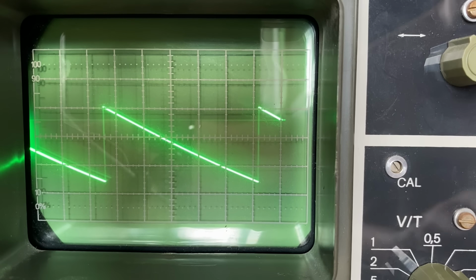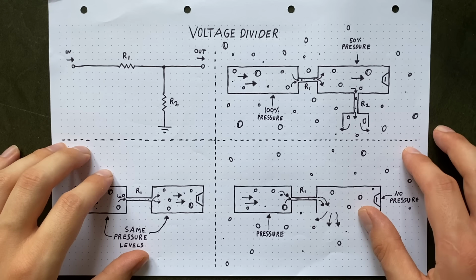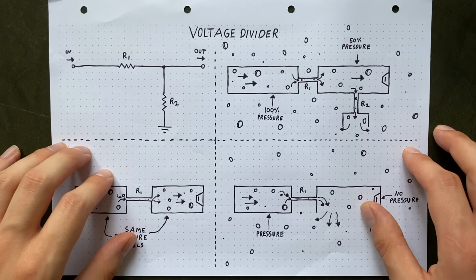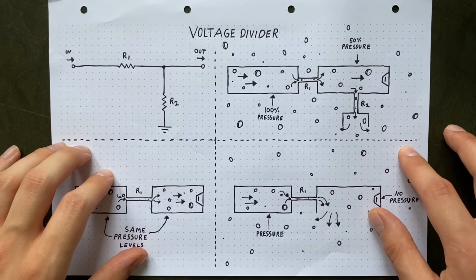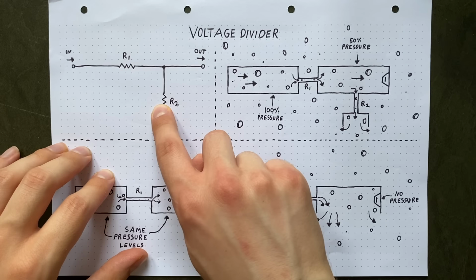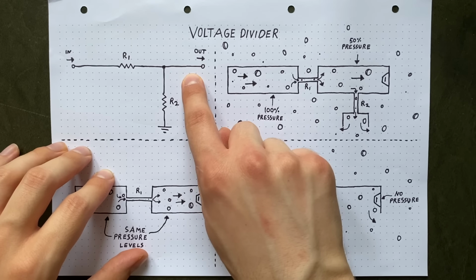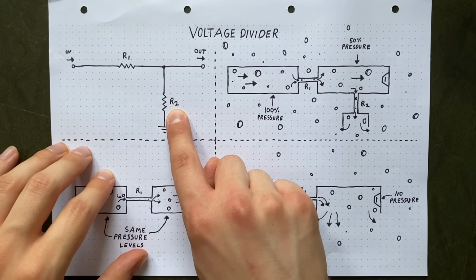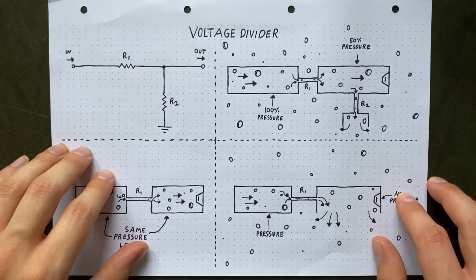So, can we listen in now? Well, we're almost there. But as a final touch, we should decrease the volume of our oscillation, because a very loud signal like this can, again, damage your amp or your speakers. To do that, we will use a voltage divider, which is just 2 resistors set up like this. Here's the input, and over here is the output. If R1 and R2 are the same size, the output voltage will be half of what the input voltage is.